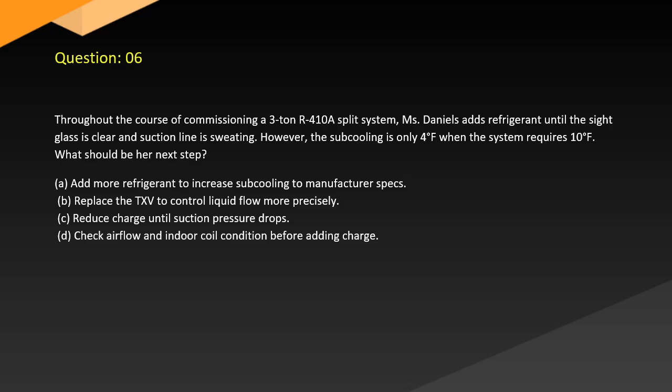A. Add more refrigerant to increase subcooling to manufacturer specs. B. Replace the TXV to control liquid flow more precisely. C. Reduce charge until suction pressure drops. D. Check airflow and indoor coil condition before adding charge.